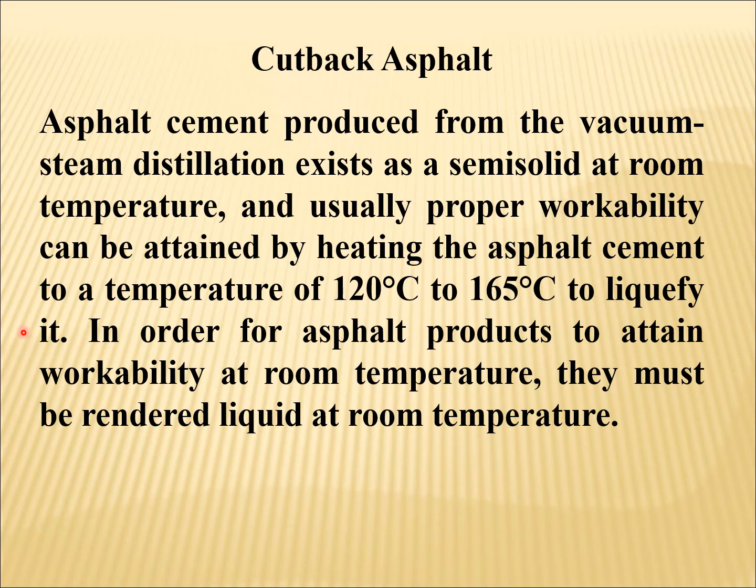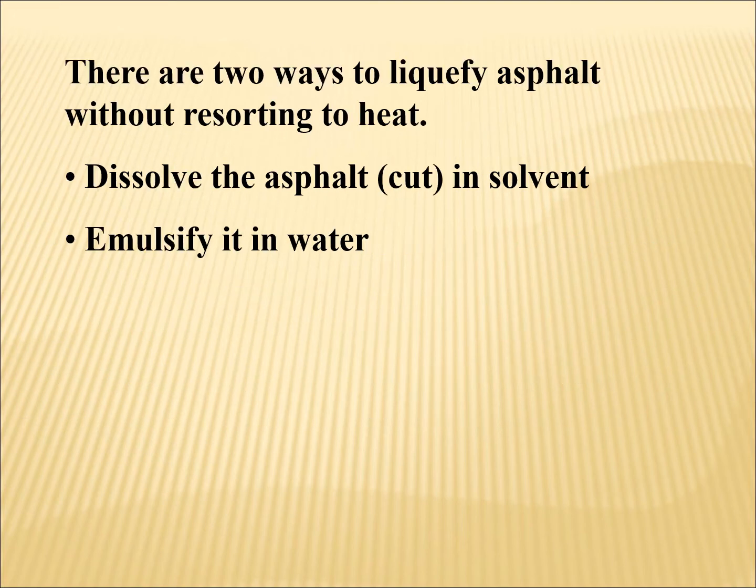In order for asphalt products to attain workability at room temperature, they must be rendered liquid at room temperature. There are two ways to liquefy asphalt without resorting to heat. Dissolve the asphalt, cut in solvent, or emulsify it in water.